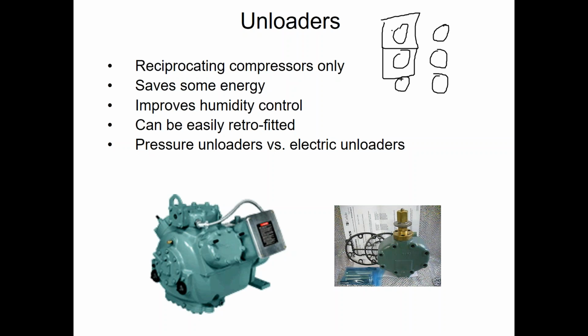So I can get a lot of stages this way, right? I can have stage 1 turn on, stage 2, put all of it on for stage 3. Then when I want stage 4, I can stop using compressor number 1. I can turn on compressor number 2 in its entirety, and then just keep compressor number 1 loaded over here. So I can have the second compressor on, so stages 4, 5, and 6 would be on along with 1. And then 4, 5, and 6 with 1 and 2, and then all 6 of these could be on. I can get 6 stages by putting 2 unloaders on the lead compressor and having a smart control sequence.